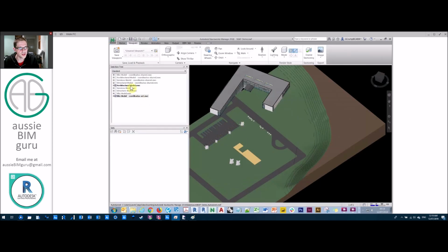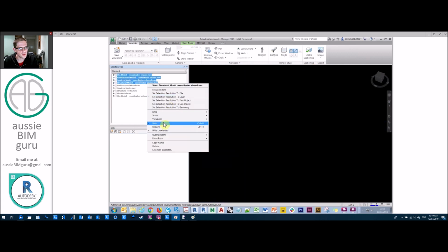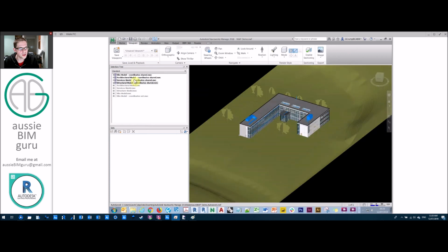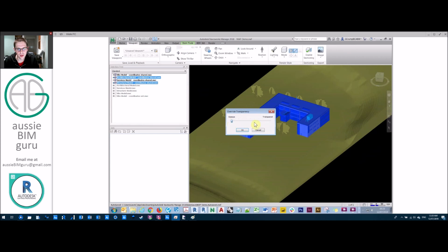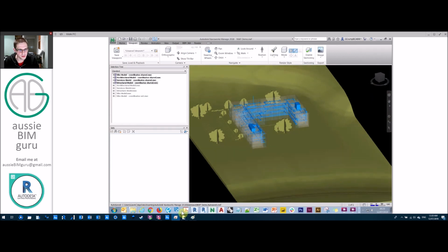And if I just jump back into Navisworks and I take the outcome, so the NWCs that I've exported earlier, you'll see we have a fully aligned site, which is great. So everything's coming together, which is exactly what we want. So if I just say ghost out these, you'll see that our services should be sitting in the right positions in the building. So there you go. So we have a coordinatable project now, which is brilliant.